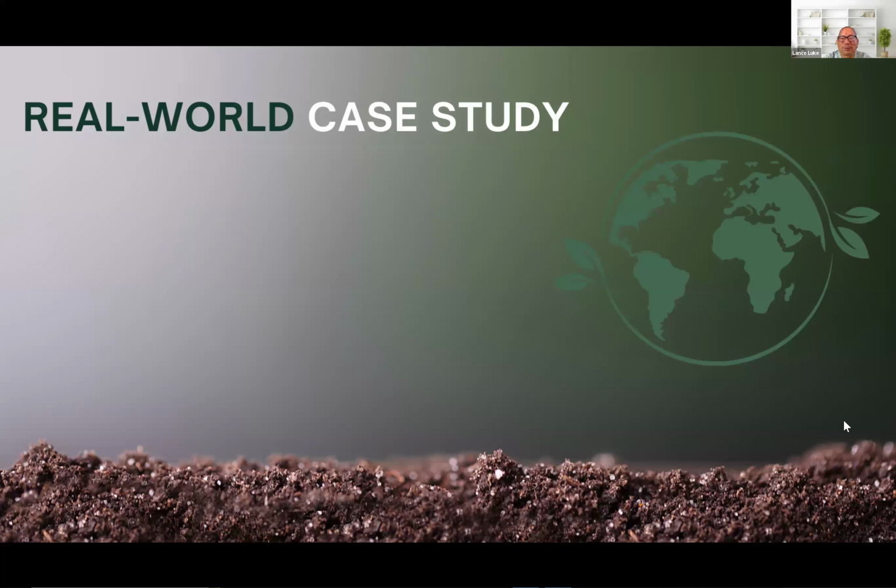So I get there, and I said, well, let's go into one of the bedrooms and see this big crack you're talking about. And sure enough, the grout was there, but the CMU blocks that are supposed to be together had separated, and the crack was big enough that I could see light coming in. I go closer, and guess what? I see the neighbor watering his yard. That's how big the crack was. And I'm thinking, okay, this homeowner really wasn't exaggerating.